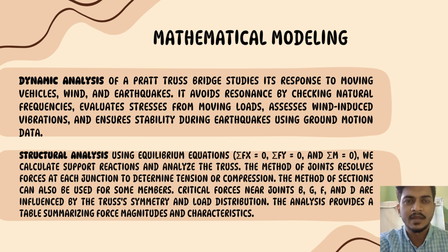In this slide we can see two types of analysis: the first one is the dynamic analysis and the second one is the structural analysis. At first we can talk about the dynamic analysis. The dynamic analysis of a truss bridge studies its response to moving vehicles, wind and earthquakes. It checks the natural frequencies and the equivalent stress from the moving load, assesses wind, including vibration, and ensures stability during an earthquake using ground motion data. It's very important for any bridge.